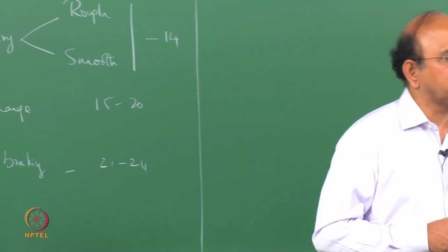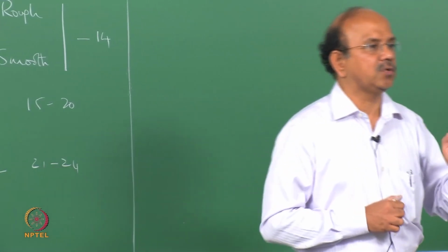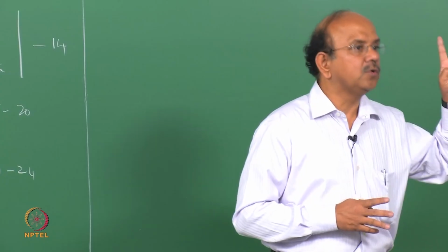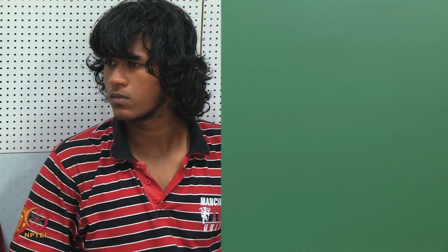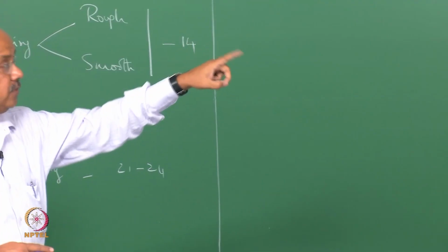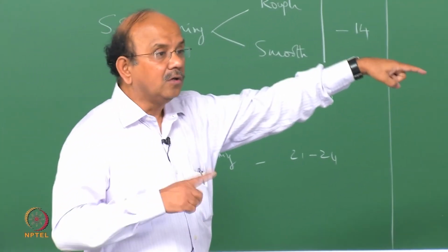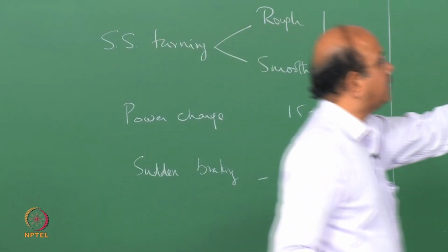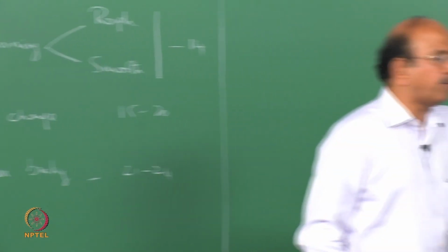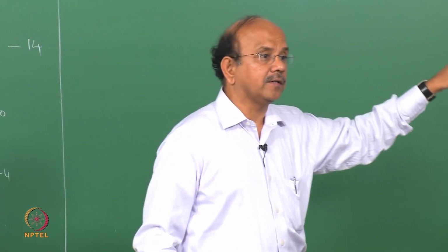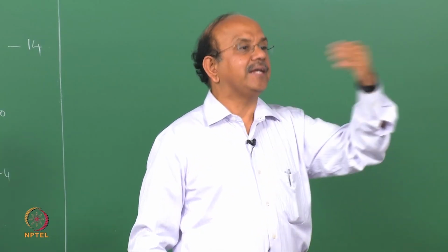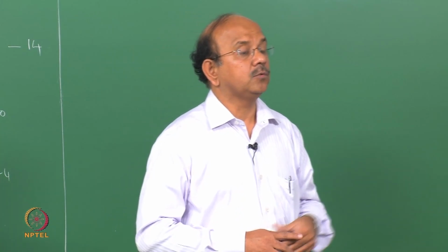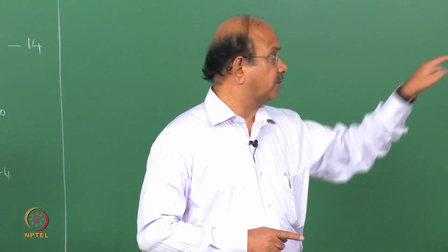When you do a transient understeer or transient oversteer, the drivers also do not want surprises. So that's why we do such a subjective rating. Once I do a subjective rating and a subjective-objective correlation, my design also becomes simple. Now if I tell you that my yaw rate gain at 0.7 hertz is important, then my next goal, which you will do in the next course on vehicle dynamics lab, is to find what design parameters are going to have an effect.